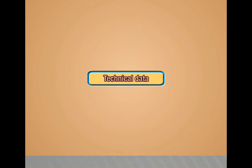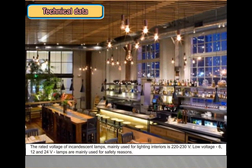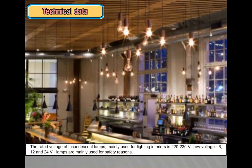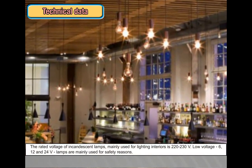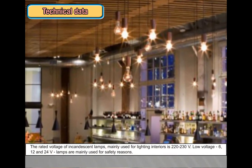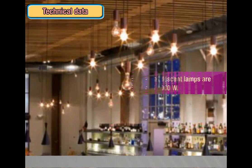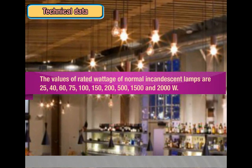Technical data. The rated voltage of incandescent lamps mainly used for lighting interiors is 220 to 230 volts. Low voltage 6, 12 and 24 volt lamps are mainly used for safety reasons. The values of rated wattage of normal incandescent lamps are 25, 40, 60, 75, 100, 150, 200, 500, 1500 and 2000 watts.